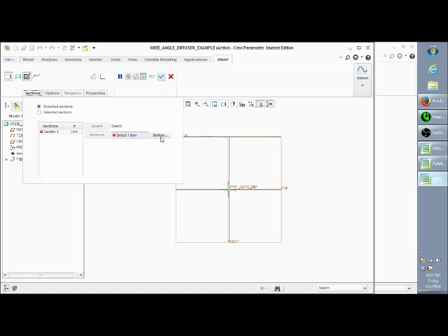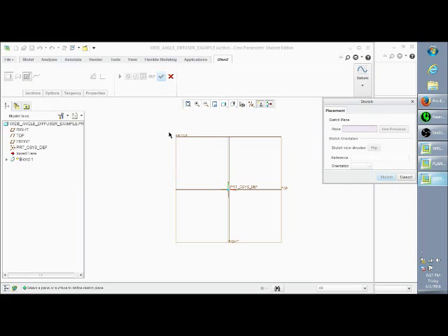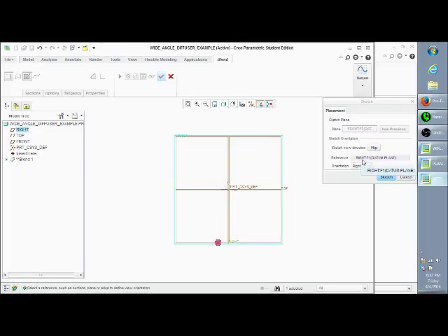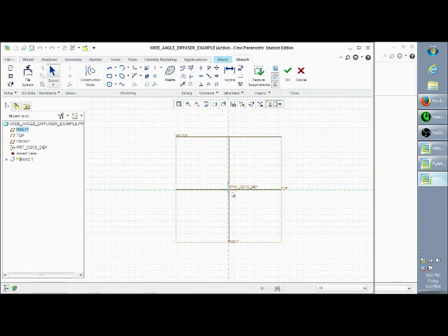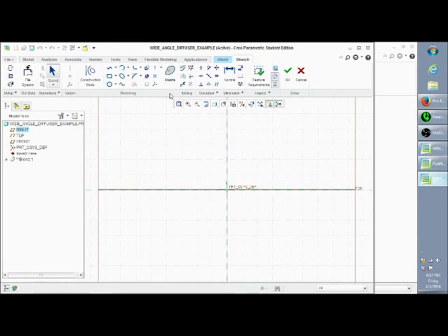So in this view, we're going to sketch the smaller face first. What you want to do is go to Define, and then for our sketch plane, we want to select Front. And then we're good with whatever reference pops up, since only really two should pop up, and that's the top plane or the right plane. So you go ahead and select Sketch. Okay, so we can start creating our shape.